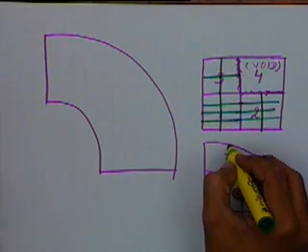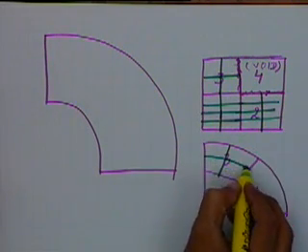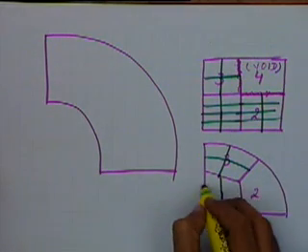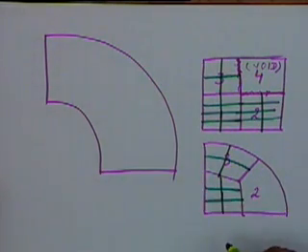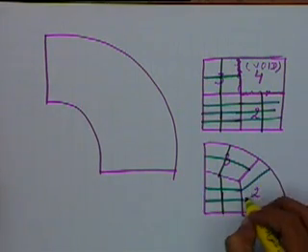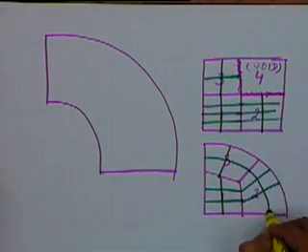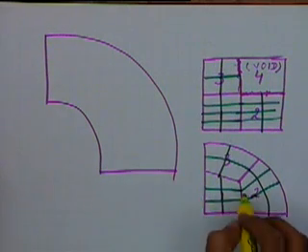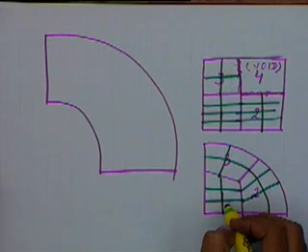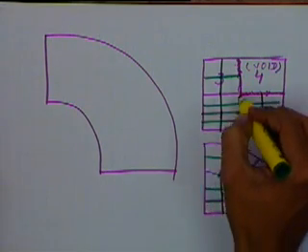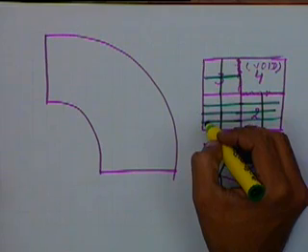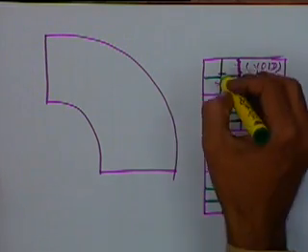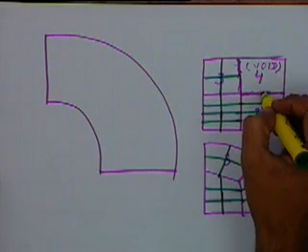So here I will get a mesh which will look something like this. Here I will get a finer mesh, and similarly here also I will get a finer mesh. So depending on the portions where I want to have a fine mesh, I can choose a different mesh density in different blocks, and then merge the edges which are to be joined together.